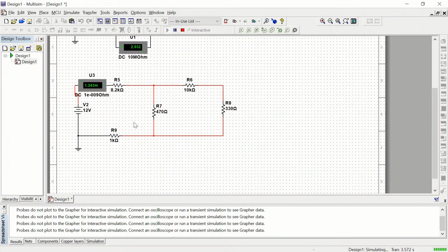So you're going to place an ammeter into your circuit and give the overall current in the circuit, and then pick one of the branches. What I want you to do is demonstrate that you know how to put the ammeter into the circuit so it goes in series with the components, where the voltmeter is in parallel with the component, and to demonstrate that you have some proficiency at Multisim, and you can get into the circuit and you can delete stuff.